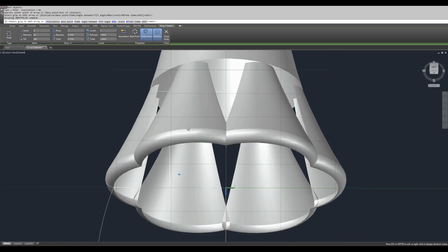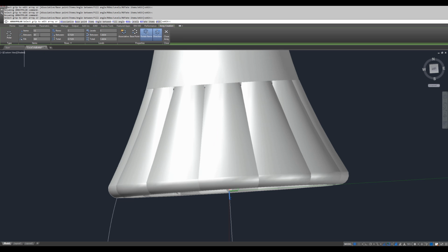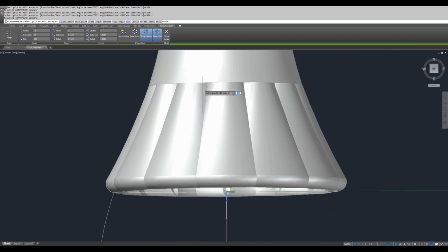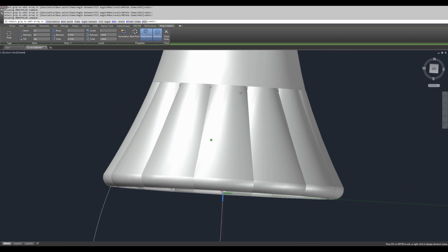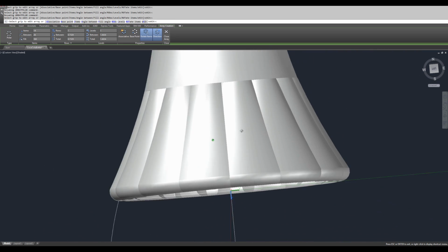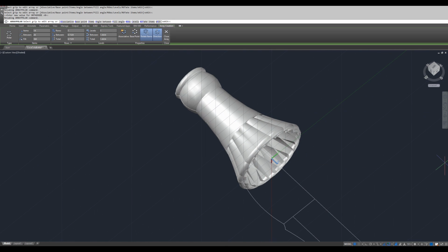However, there's like a large amount of gaps in between it. So we're going to increase the number of items that we have. And let's go ahead and try 12 items. And then I'm just going to click to the one underneath it. And if you take a look there, you can notice that there's been a significant reduction in gaps. But nonetheless, there are still a few gaps. So let's adjust it to 14. Click OK, and that's looking much better. So that's looking good so far.